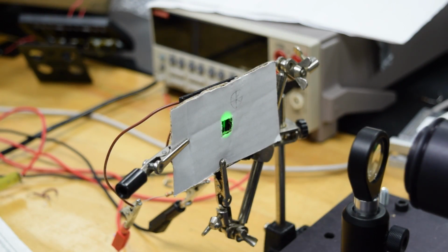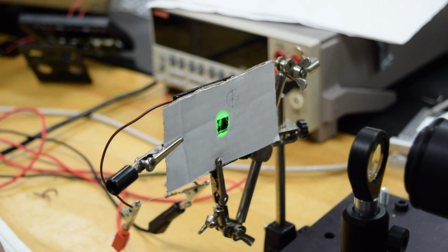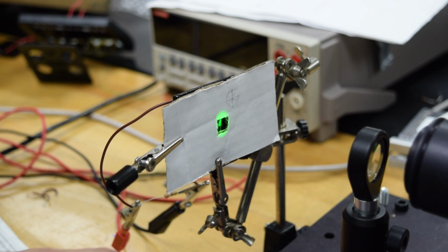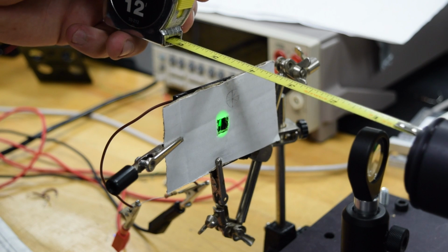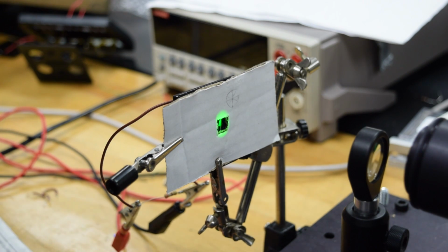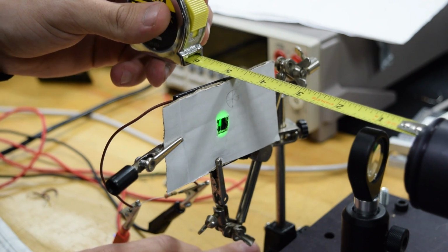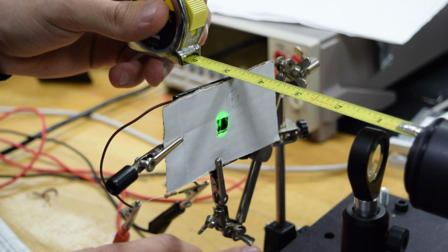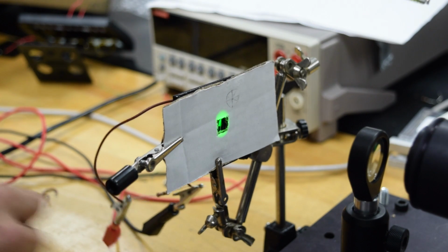Once we've got our solar panel into our optics mount, we're going to set it up so that the surface area exposed is being completely flooded with the beam of light, as we can see in the video. I'm also going to make sure that my solar panel is set at an arbitrary distance away from the light source, and we're going to match that arbitrary distance when we do the readings for our power meter. So for this measurement, I'm going to keep the power meter and the cell at 5 inches away from the light source.